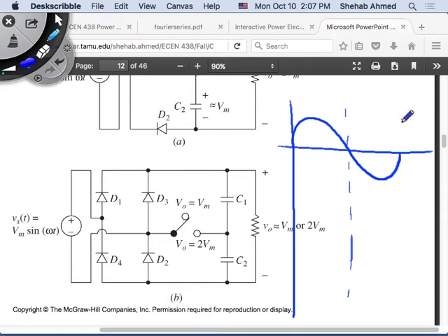What's happening in the positive half cycle? So now I will have this switch. When the switch is open, how does the circuit behave? It's the same as the one above. No, when the switch is open. It's two capacitors in series. But what's the output voltage waveform? Same as the full wave. Exactly. The output is a full wave rectifier, like the full bridge diode rectifier, right? The output is just this rectified waveform if the switch is open, right?